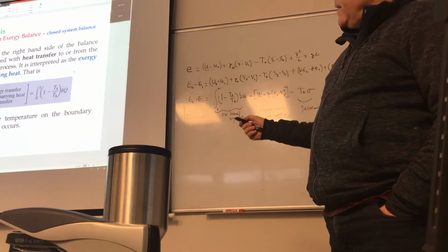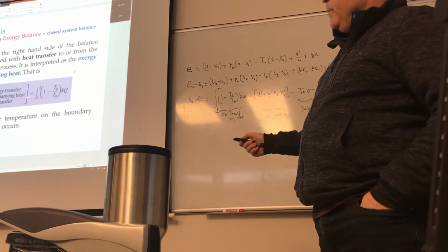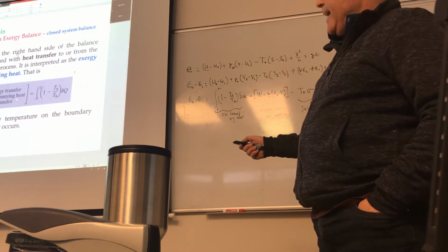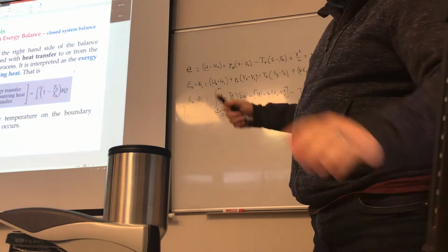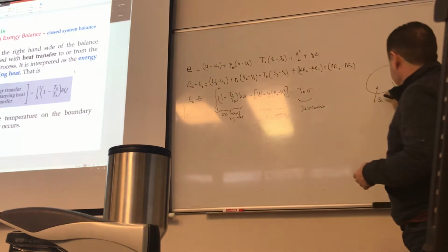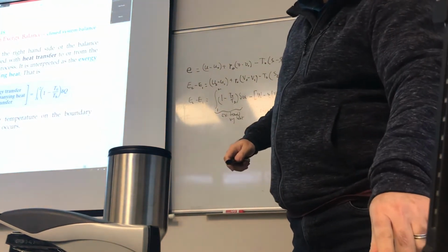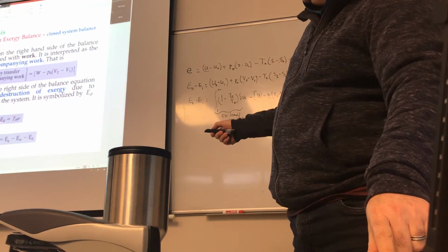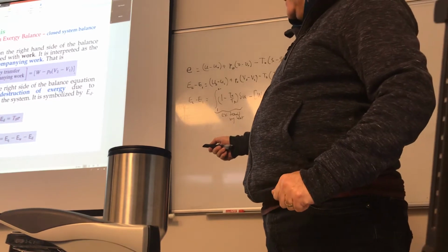Then we talked about every single term. The first one is the exergy transferred by heat transfer. And remember what TB means. It's really the boundary temperature, because as the heat is going through here, it is whatever the temperature of the boundary is going to be. And then work is the same. And lastly, E destruction is T naught times sigma, okay?